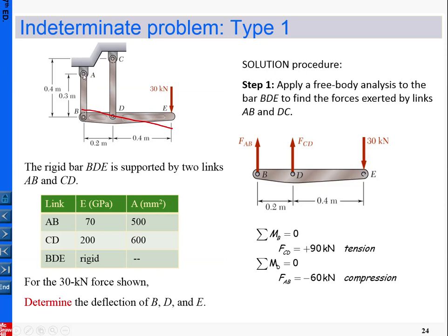Here for this support, AB and CD are deformable, which means Hooke's law and our learned stress analysis apply to AB and CD. So that is this equation here. This rigid BD performs as rigid, doesn't deform, but it inclines. It always remains a straight line. So basically, this provides us a hint for formulating additional information for solving the problem.